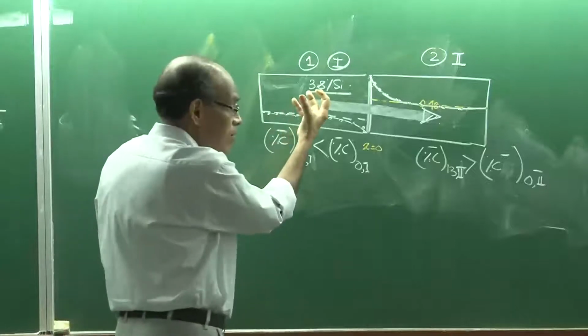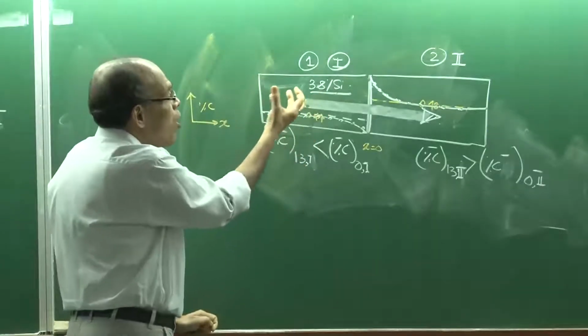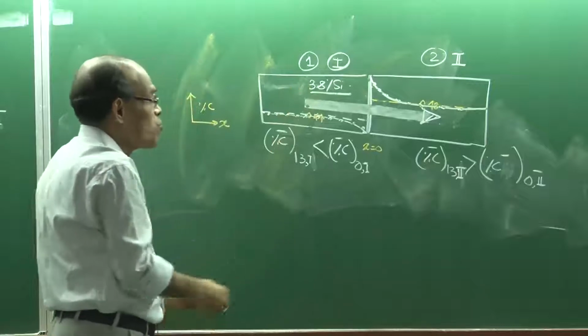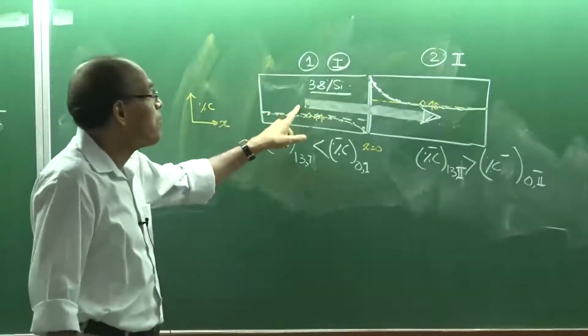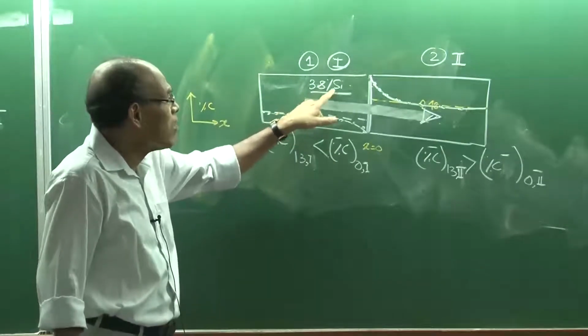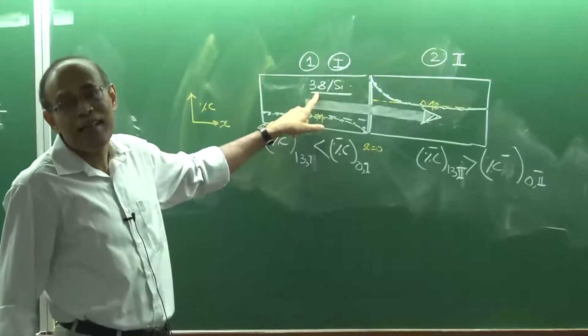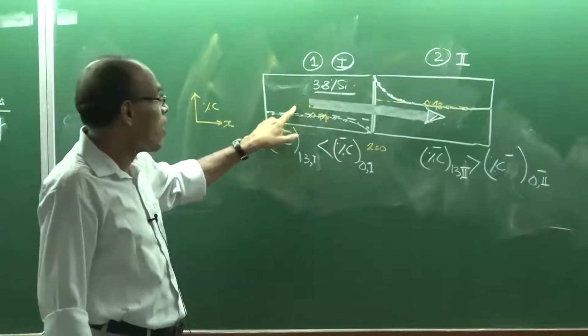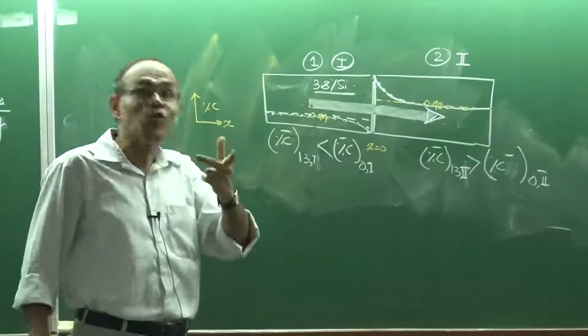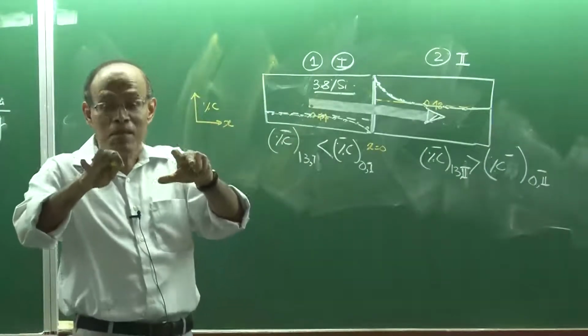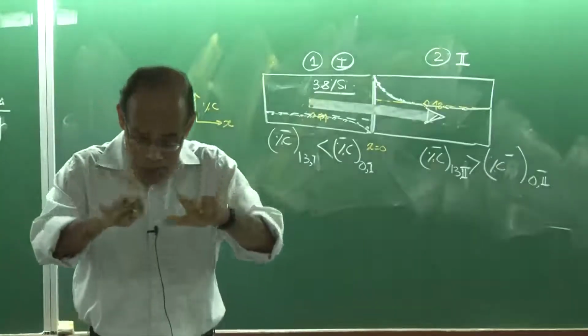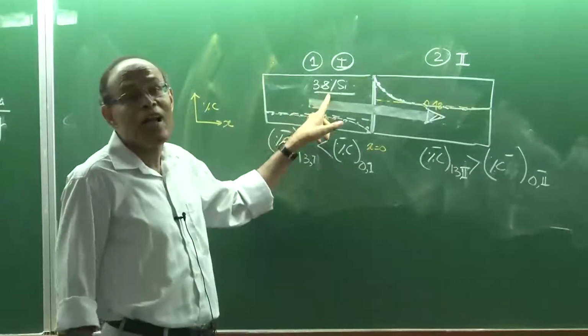In that case, the activity of carbon actually can be reduced. Suppose, for example, I use here, instead of silicon, strong carbide forming elements like niobium, tungsten, etc., then whatever I am saying is going to be reversed. The activity of carbon now is going to be even down from the activity in the original alloy, because